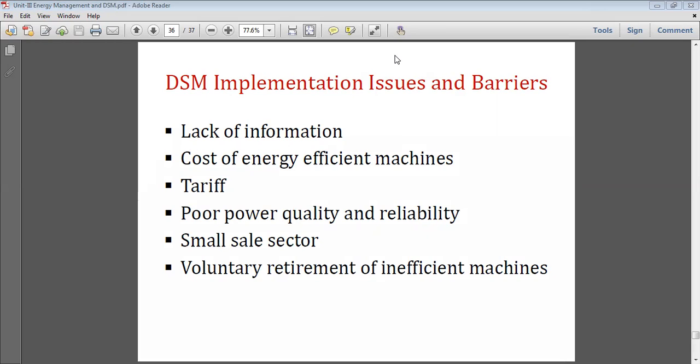As such type of people are not educated toward demand side management, energy management, the present scenario, as well as power factor improvement and its detailed calculations, such small scale industry uses some thumb rule, and they will connect some fixed capacitors. In the night time, the power factor will be unity, isn't it?